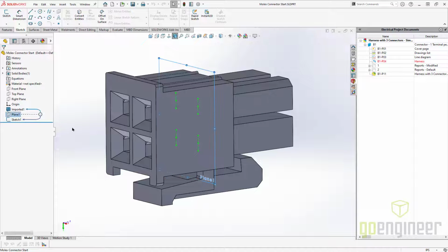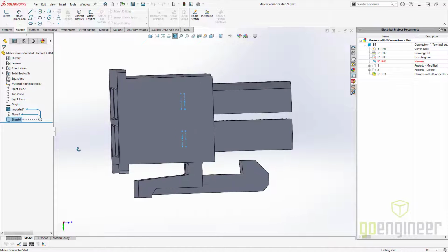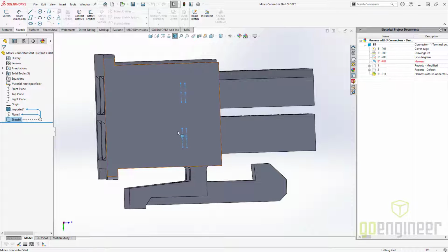The only thing I've done so far is I've established a reference plane and then a sketch of points. And really what I usually shoot for with any component, but more specifically with connectors, is I try to find a spot in the connector where the wire stops. So if I shove it into a pin and I shove that pin into this connector, where does the tip of that wire actually land? The reason I do that is it gives me the most accurate length on my wire coming out of the connector. If you put it on the face, then you're going to be short the strip length. Yes, there is a calculated value that you can type in there, but I like to just put my sketch points in ahead of time.